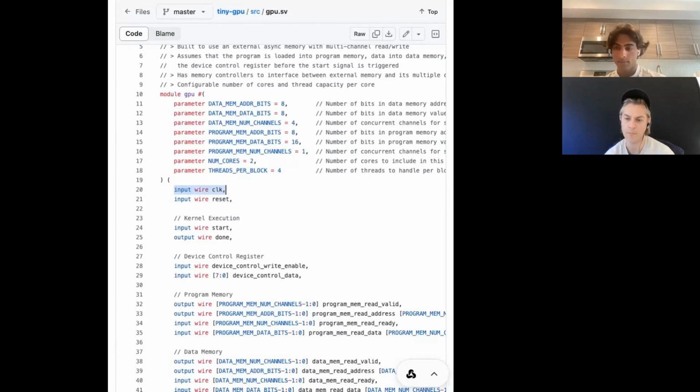Gotcha. Okay, cool. So if something is waiting, it sounds like you could implement this in probably a lot of different ways, but you could have your cores sort of saying, I'm in waiting mode, so this cycle I basically just do nothing because I'm still waiting for the memory to return. And then next cycle, if I got it back, then I can actually do it. And because there are different latencies, they can just diverge in terms of where they are in their particular execution flow.